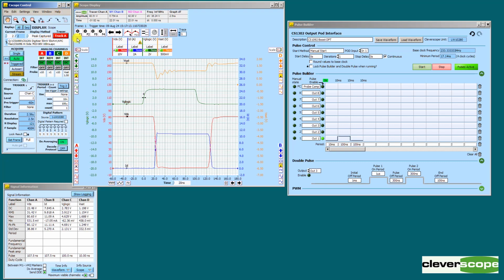Now we can work out the delay more accurately. So let's go back to VLogic, and we can do that by clicking on this control and place a marker at the center point, 1, and going back to the current, there, and placing a marker there, 2. And we see the time delay through the gate drive and the actual device at 22.14 nanoseconds.